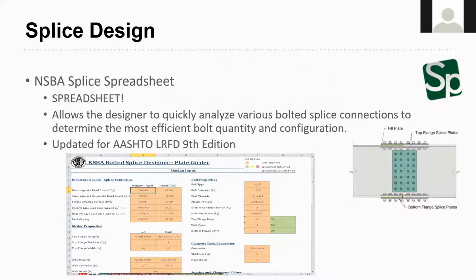Now, I'll say, go ahead and use the splice spreadsheet, but be aware of the calculations. Run through an example calculation or two so you become confident and familiar with it. Use the examples that are provided in that NSBA guide that I just showed previously, and understand what calculations are going on behind the scenes.